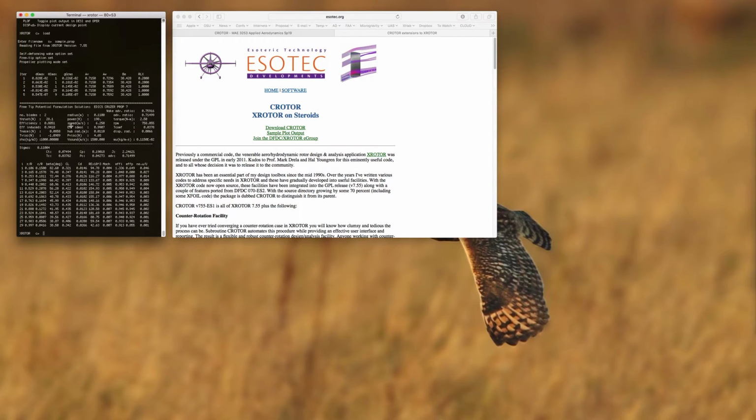Speed of the aircraft, so this is your flight speed, is going to be in meters per second. You'll also have RPM, as well as viscosity that you're working with. Your Reynolds number and density will be calculated off of those. Speed of sound, so that way you know what the tip Mach number is going to be, which is an important propeller defining characteristic.